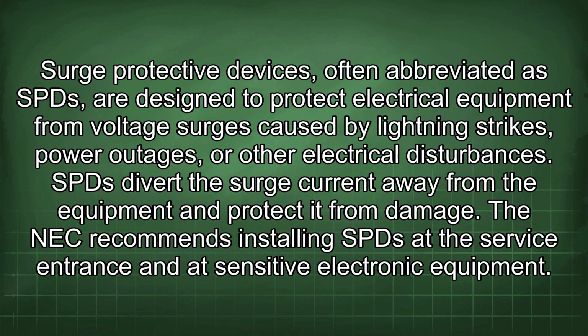Surge protective devices, often abbreviated as SPD, are designed to protect electrical equipment from voltage surges caused by lightning strikes, power outages, or other electrical disturbances. SPD divert the surge current away from the equipment and protect it from damage. The NEC recommends installing SPD at the service entrance and at sensitive electronic equipment.